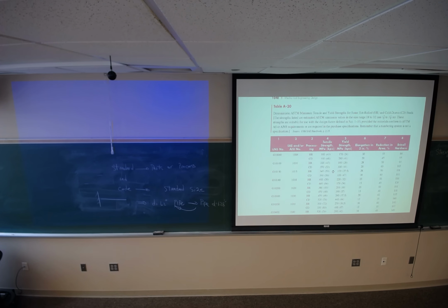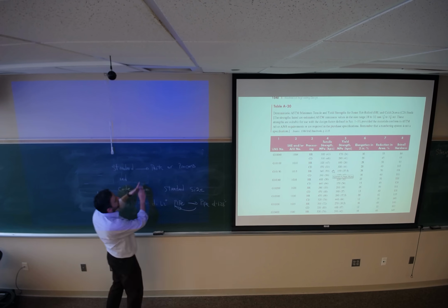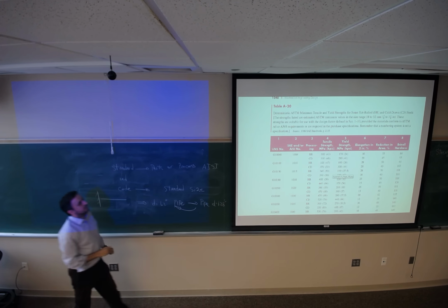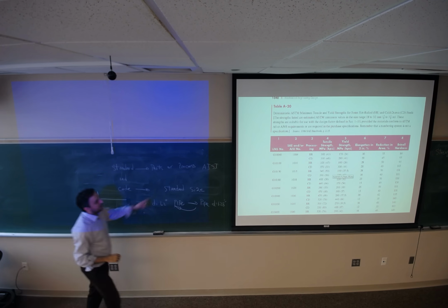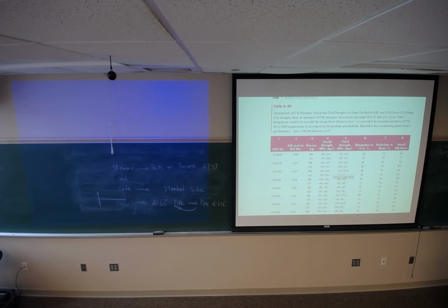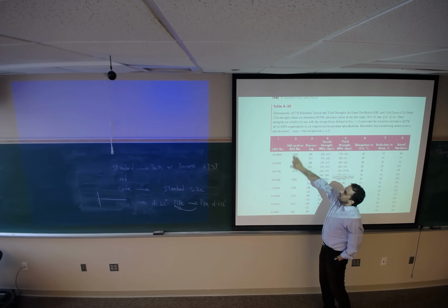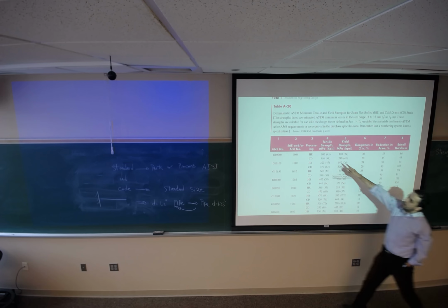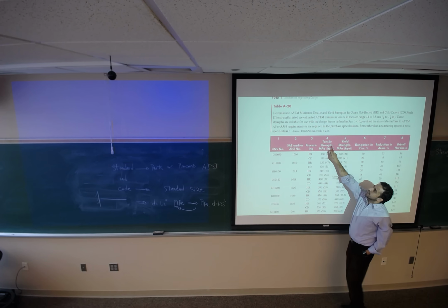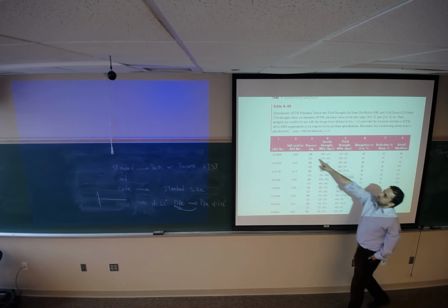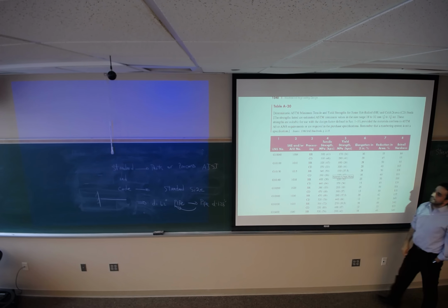You remember I told you on the standard part, one of the organizations that you will see is AISI, American Iron and Steel Institute. This is the standard for the steel. AISI number 1006: if the processing is hot roll, the tensile strength is 300 megapascal, and the yield strength for this material is 170. This is table 820.